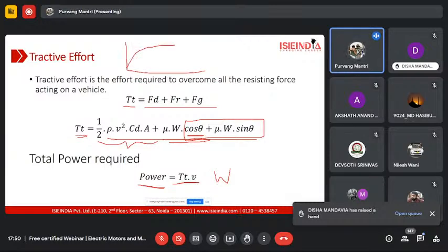It is like sort of a gradual curve. It increases linearly and then it flattens out. But in case of motors, the torque that it can provide is pretty high at first instance, at initial stage, and that it reduces with time. So this is what is highly desirable for our vehicles, and in that case, it was recommended to not use the first gear for that retrofitted Desire.